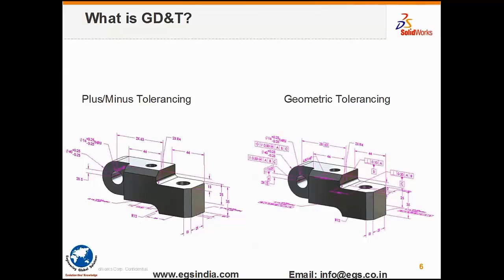In addition to providing additional tolerances, if the setup and the manufacturing allowables are going to increase as you move away from your specified material condition, you get what is called as the bonus tolerance. This is where GD&T scores over the plus or minus tolerancing methods. From 1994, when the previous standard of the ASME was announced, and 2009, 15 years have passed, where the manufacturing industries have been requested to transition from plus or minus tolerancing to geometric dimensioning and tolerancing schema.